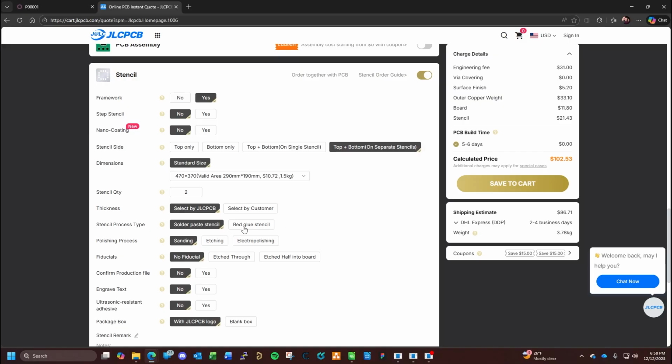So you can place the SMT parts on the bottom using a special adhesive, basically a glue, and it places the parts and they get glued to the PCB, but there's no solder paste. You're basically gluing instead. Then you pick and place as normal, the glue sets while you're doing other things, and then you put your through-hole parts in, and then you put that assembly into a wave machine, and it solders everything all at once. It solders all the through-hole parts, and it solders the SMT parts using a wave machine.